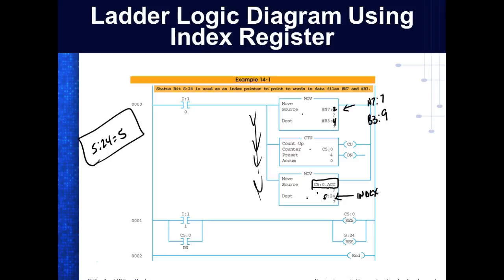Yeah, so normally I would put this guy here first, but like Larry's saying, the sequence would be so fast that you would never see the first scan. Slow it down? No, in a real PLC, you cannot change the scan time. Everybody understand that? So that's set into the processor.